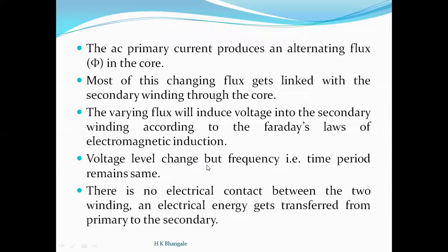So the voltage level changes, but the frequency, that is the time period, remains the same. No doubt, whenever this transformation of energy takes place from one circuit to another circuit, the voltage level changes. But whatever the frequency of the input signal, the same will remain at the output. There will be no change in the frequency.